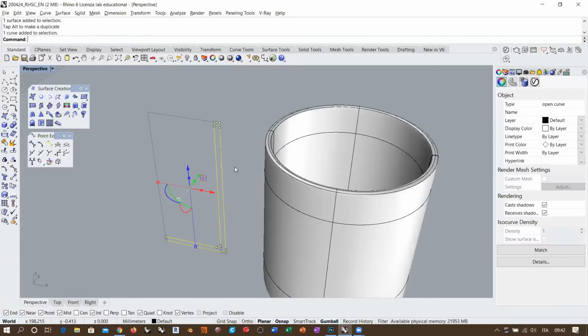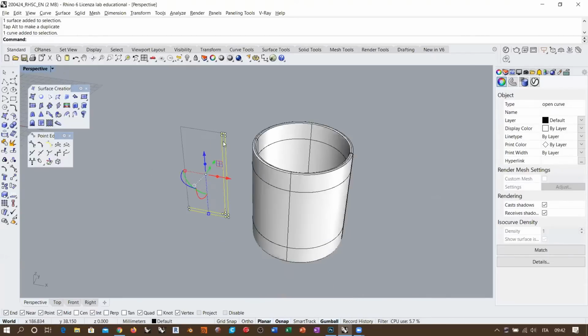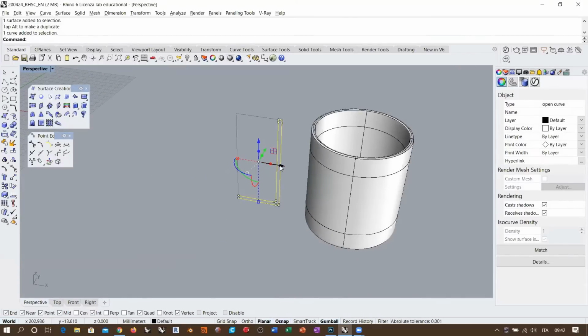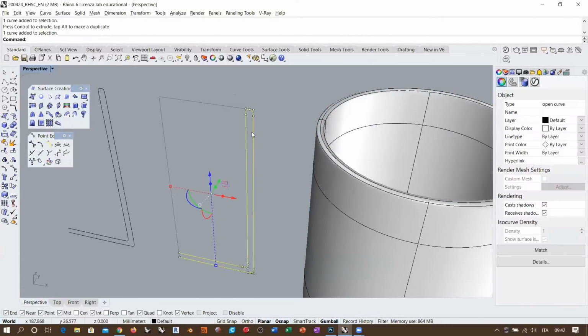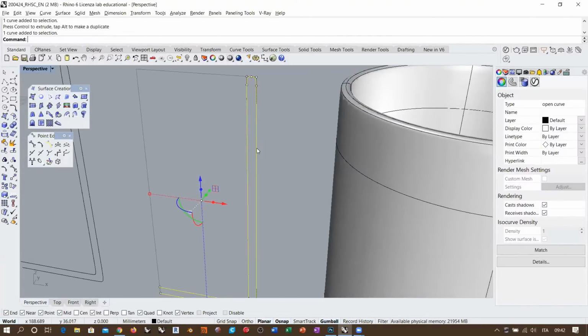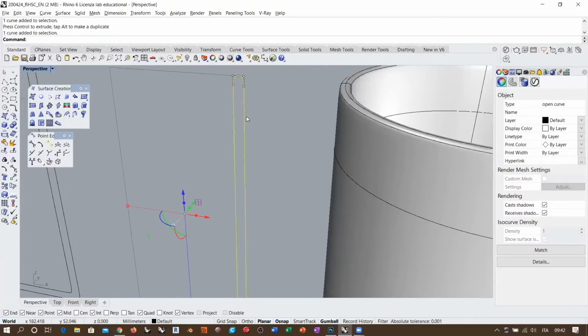First thing that I can do is take the original profile and let's also preserve the original profile here, okay. So I always have the original curve, and then take this one, and as I need to create a bulge, for example, here, and I don't have control points, what I need to do is to change the profile topology, okay.